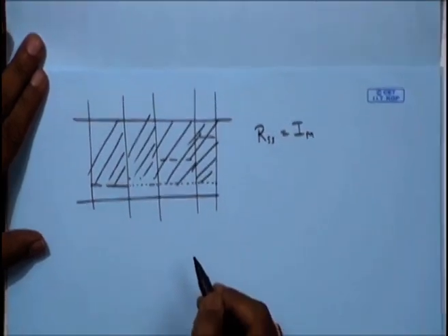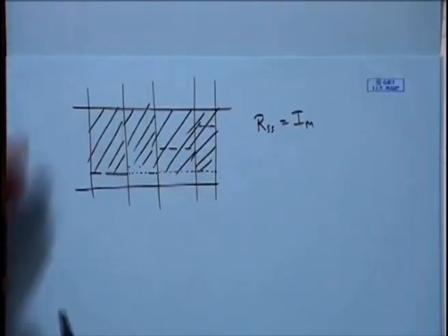So there again we see that if equal power is allocated under such conditions, that means when you have very high SNR, all you need to know is the rank of the channel and you can give equal power to them. Whereas when SNR is low and when eigenvalues are not equal, in that case it is better that you identify the rank of the channel and allocate power to those modes where the eigenvalues are non-zero or where eigenvalues are significant, and you give the power depending upon the strength of the eigenvalue.